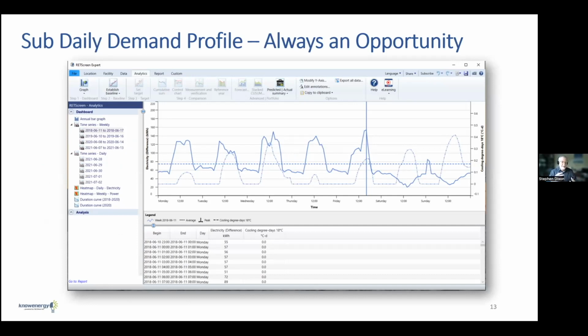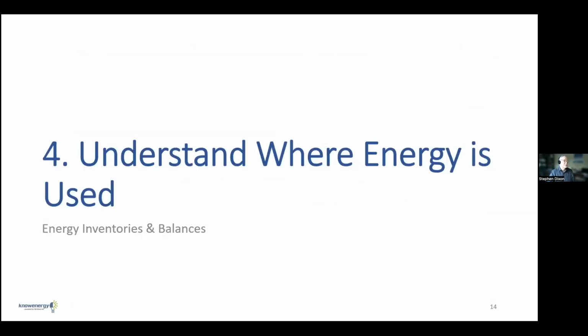If I'm doing an interactive session with people, I can do heat maps. I can do load duration curves. I mean, there are so many things we can put on the graphs here. But what I love to be able to do then is overlay the parameters of influence, things like, in this case, cooling degree days, and see how warm it is outside driving the electricity demand for that building. Again, all of this in the same toolbox. Understanding where energy is used. Any audit, I was taught years and years ago, the most important thing to do in an energy audit is to understand where it's all going.